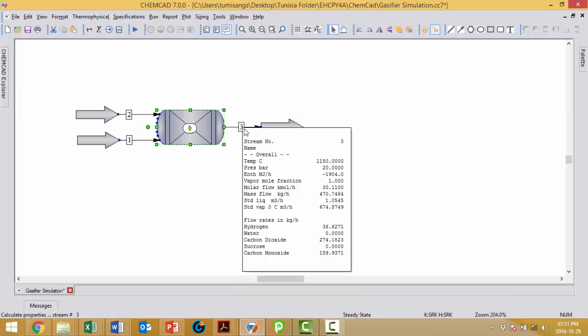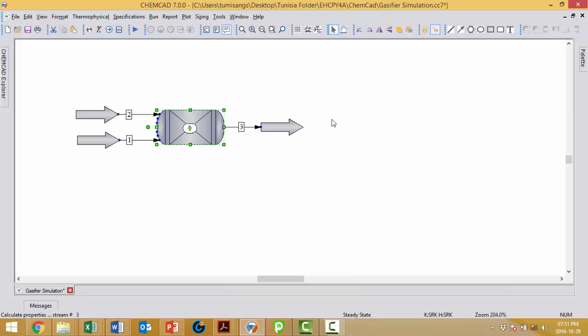So the stoichiometric coefficients we have do not have to be changed because they balance perfectly in the significant figures that we have supplied, and Chemcad does not seem to have a problem with that, and we have to be happy with that because now we don't have to enter numbers with long decimal places. So at this point, our gasifier works well and the simulation is complete. We can proceed to the next phase of the lecture.